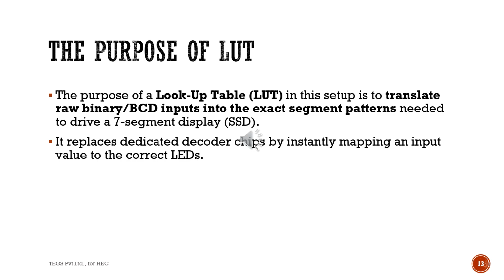The purpose of creating a lookup table. The purpose of the lookup table in this setup is to translate the raw binary BCD input into the exact segment pattern needed to drive the 7-segment display. It replaces a dedicated decoder chip by instantly mapping an input value to the correct LEDs.